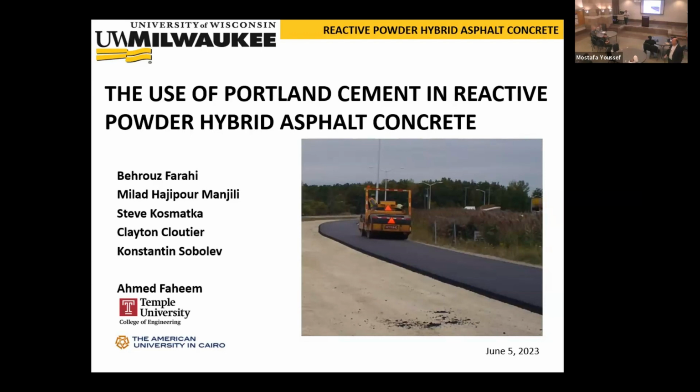The only interaction of the powder and the bitumen is the role of cement in self-healing at a very late stage, when the asphalt is already breaking or cracking because of age, etc. I guess you will have the same thing with silica. Okay, well, yes, we can give it a try. That's what I'm saying, because in this case, you're not using cement for its hydration property, because of the temperature.